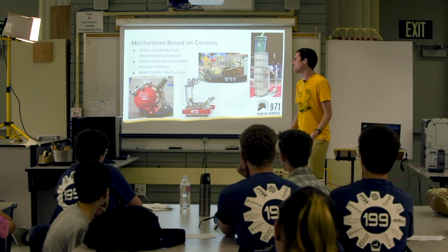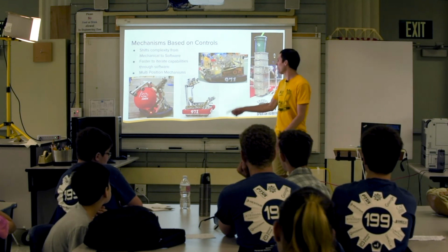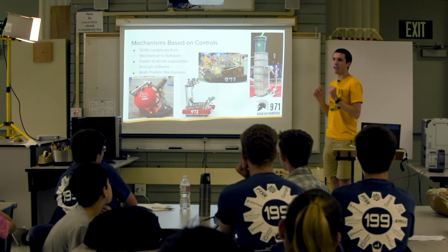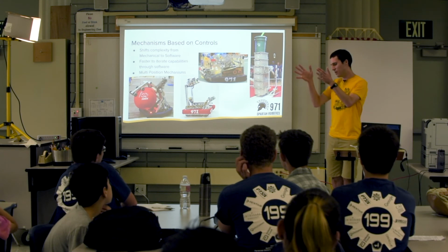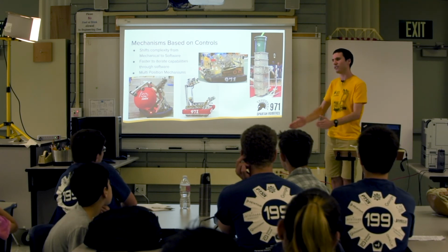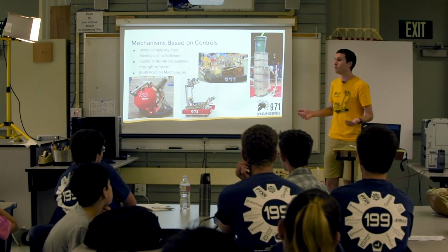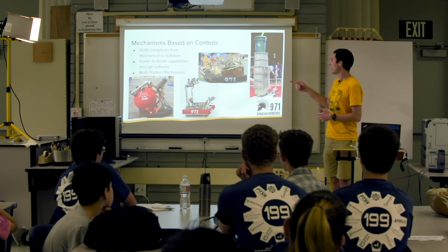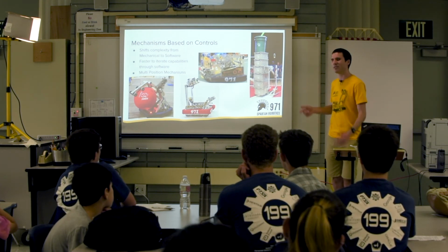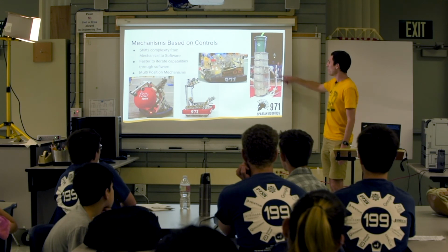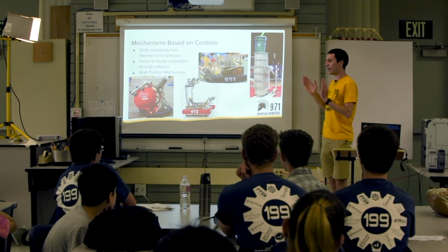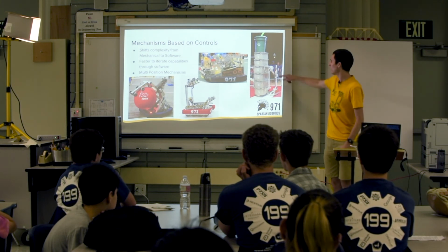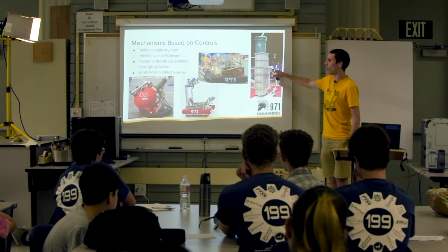So yeah, and then 2015, this one was a little silly, would not recommend it again, but we wanted to be able to set the stacks down without tipping them at all. Turns out that wasn't important. We missed on the prototyping stage there. But once we had that design spec, we solved it with a mechanism. You kind of have to watch the video to understand how it fully works. But we had 2 degrees of freedom, and we could lift the stack up and then push it straight out. That was done via software coordination between 2 joints. We have an elevator up here, and then an arm here.